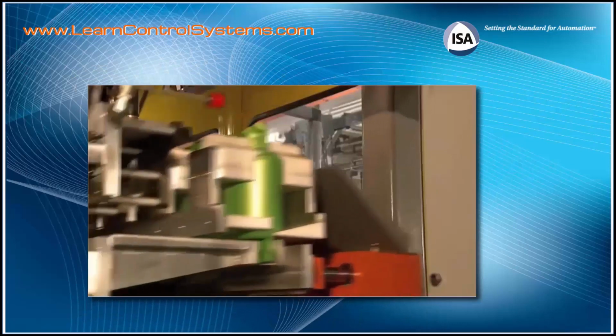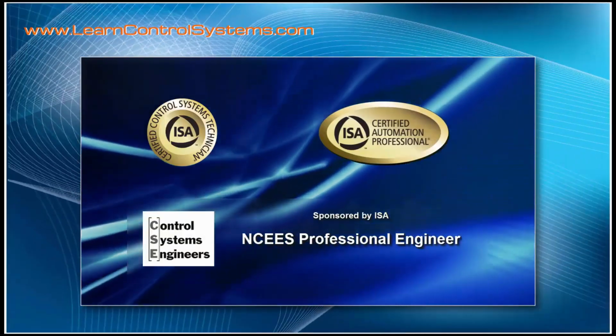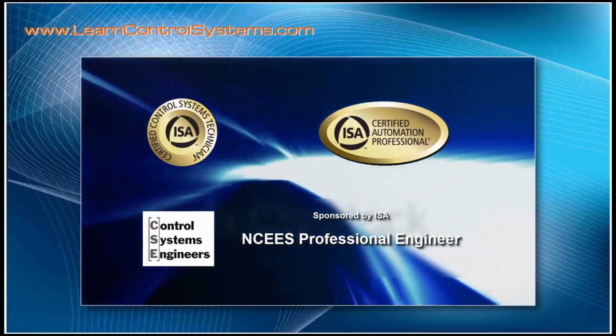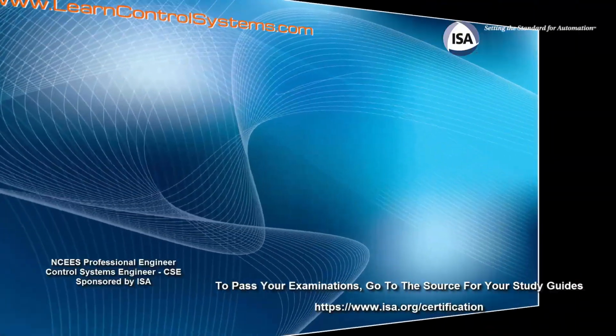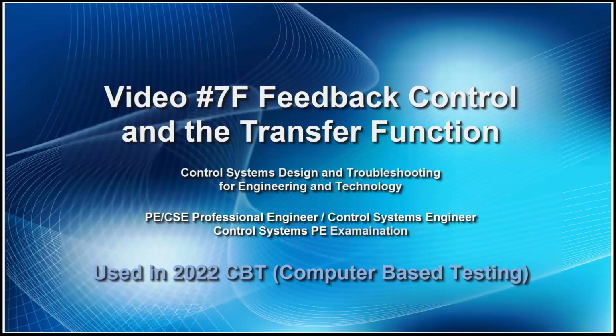We're going to focus on transfer functions and how they're actually created, and the mathematical models that follow. These mathematical models, called the transfer function, are a gain, which is just output over input. We take a set point, multiply it times the gain of the transfer function, and we have an output. We're going to show that with proportional only feedback control, there is always an offset. You never reach your set point when there's a disturbance.